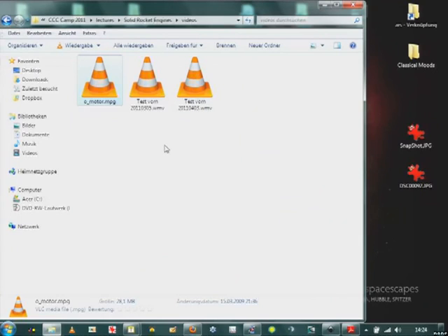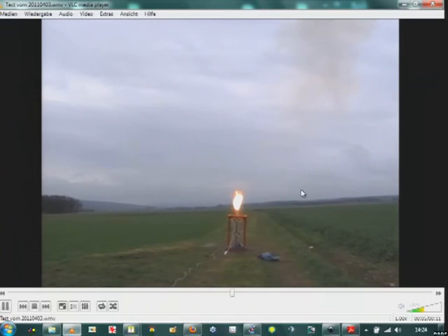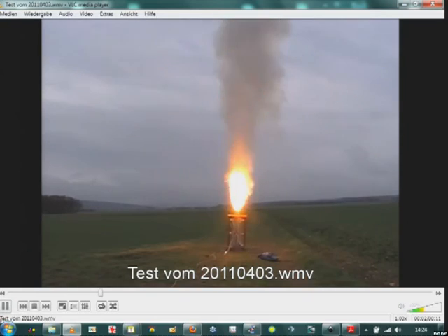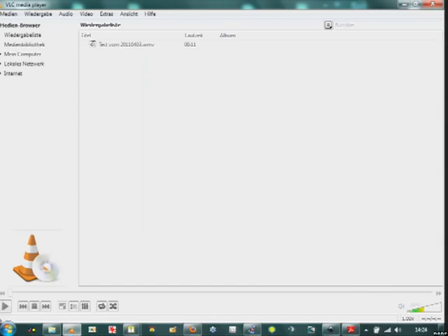And this is from this year. New grains. So just to give you a perspective, this burned for about 1 second and produced 1 ton of thrust, okay? So once again, because it was so short. Okay, and if you put this on a rocket, it will go to at least 4 kilometers or so, yes? Just with 1 second of burn. And it goes away so fast, you can't follow it. It's just, okay, that was it.